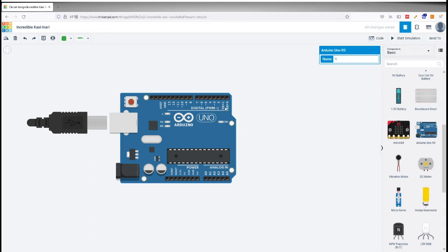And you can see that in the Arduino board there are certain digital pins. Digital pins are numbered from 0 to 13, so these pins can be used for digital input as well as digital output. On the other side, you can see there are certain analog pins named A0 to A5. That means there are 6 channel analog input pins. You can connect an analog input here, and the controller can convert it into digital format, and you can use it in the program.